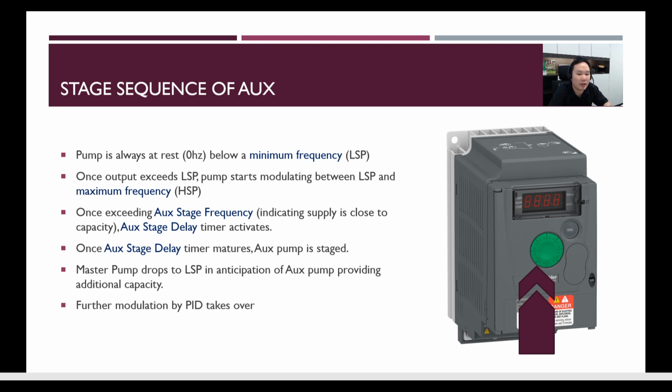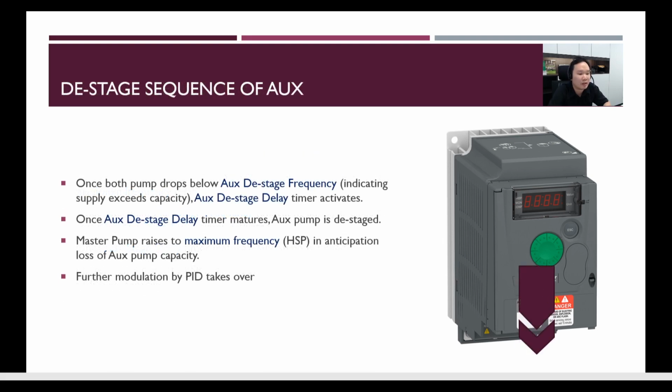The sequence is quite pretty, and I think it makes a lot of sense. Okay, so what are the steps of a destaging? Destaging is basically the opposite of a staging. Instead of bringing in the pump, now you want to get rid of it because everyone stops showering or stops using the water.